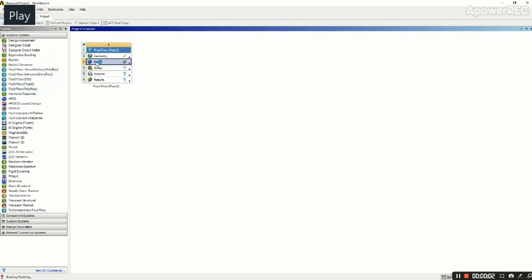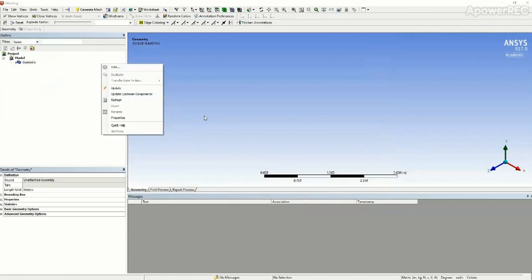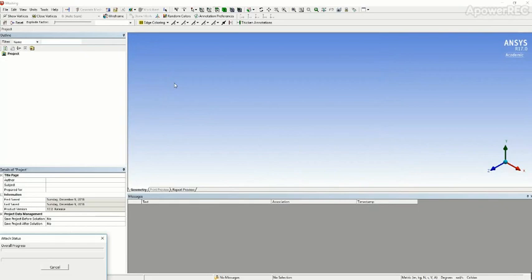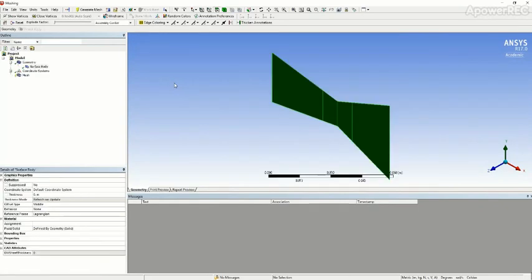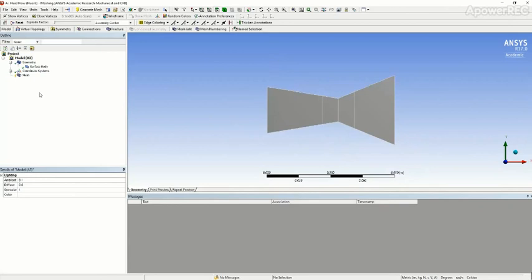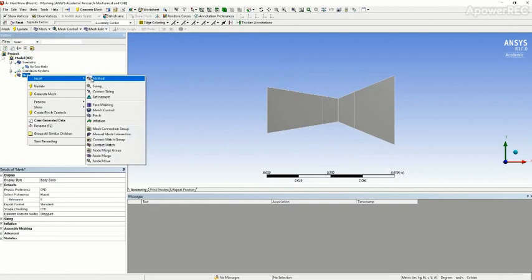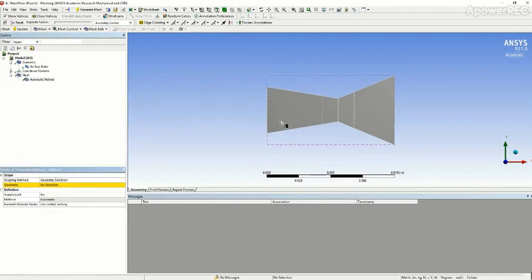Okay, now we're going to start creating the mesh. Double click the mesh part. Wait for it to generate. Then we click and change the view to the front view. Press mesh and go to insert and put method. Select the mesh, press selection, apply.